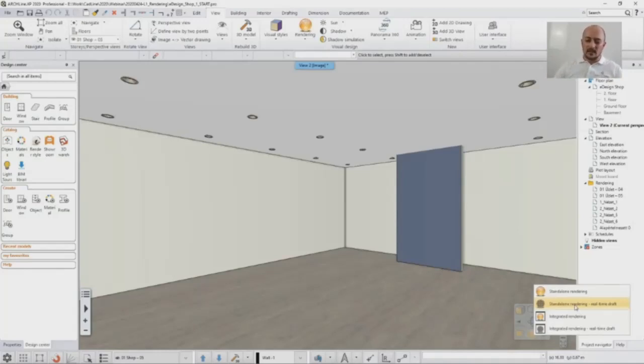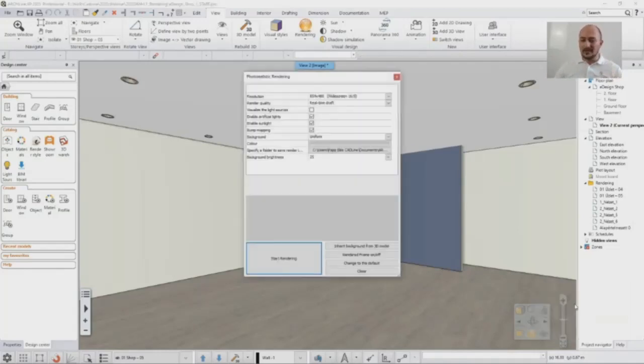And today I'm using a standalone rendering. First I will use the real time, so you will see what happens directly. And then I will show you how to turn real-time renderings into final renders. So the first thing about the rendering is the resolution and the render quality. Now, when we do the renders, resolution is key for the speed of rendering. I told you that I will talk about what sort of settings and how do they affect rendering, and resolution affects rendering time a lot.